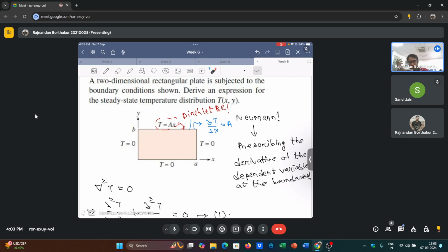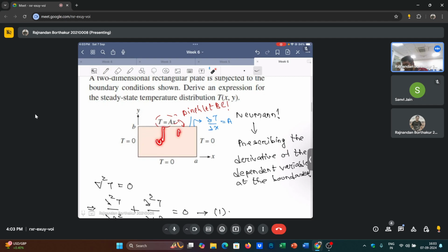There has to be a non-zero temperature field embedded in this block simply because there will be heat transfer by conduction. That means T x y equals 0 is not a physically possible solution of this eigenvalue problem, and that's why f of y cannot be equal to 0 if we want to find a non-trivial solution for our problem. Did you understand that?